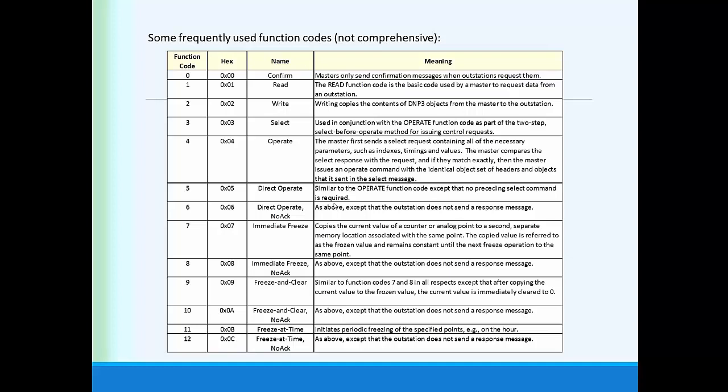So the concept of freezing counters is pertinent to this, and there's a number of ways that you could deploy this. So you could, if the meter supports it, tell a meter, I want you to freeze counters every hour on the hour, and it would just basically take whatever the reading of the register is, and set aside that reading in a frozen counter that doesn't change, doesn't increment as the kilowatt hours go on, while the running counter continues to increment kilowatt hours.